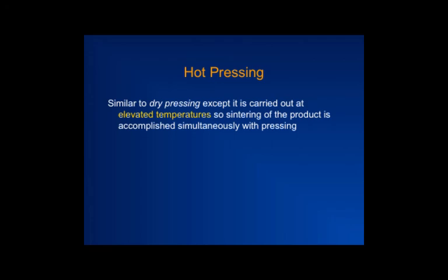What happens is, in addition, of course, you increase diffusion of atoms, and so you might get more strength in the component by the time you're done. In this case, you get to a high enough temperature, typically close enough to the sintering temperature. And so in addition to compacting it better, you're also sintering it under pressure, and there are some materials that just don't sinter well at atmospheric pressure or in vacuum. It needs additional pressure to be able to force diffusion of atoms.